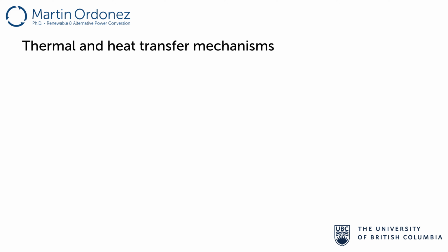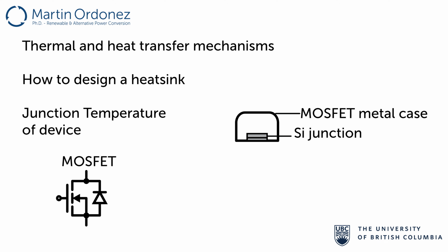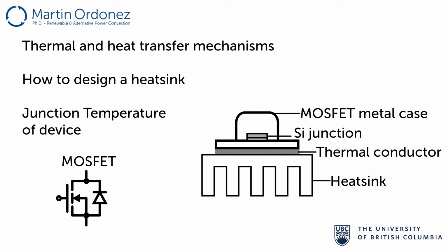Today, we are going to talk about the different heat transfer mechanisms, focusing on thermal conduction. We will also see how we can analyze its effects on the thermal design of power electronic devices, such as heatsink design and selection. Our goal is to solve a common power electronics problem from the thermal point of view, determining the steady state temperature of the junction of a device when employing a specific heatsink. As you can see, we have a MOSFET connected to a heatsink through a thermal conductor, and we want to calculate the operating temperature in different points. But first, let's take a look at some thermal concepts.